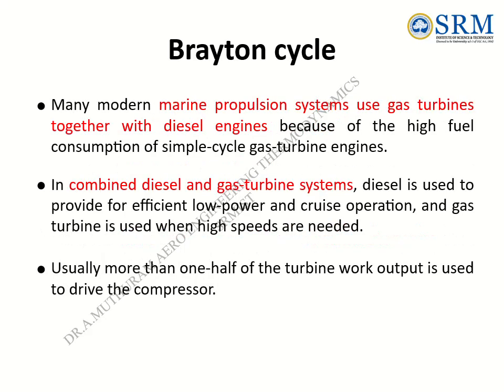Many modern marine propulsion systems use gas turbines together with diesel engines because of the high fuel consumption of simple-cycle gas turbine engines. In combined diesel and gas turbine systems, diesel is used to provide for efficient low power and cruise operation, and gas turbine is used when high speeds are needed.